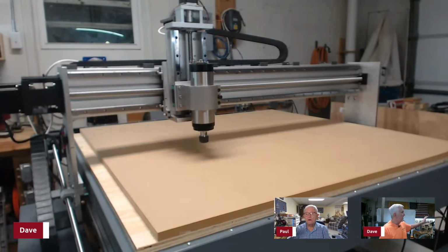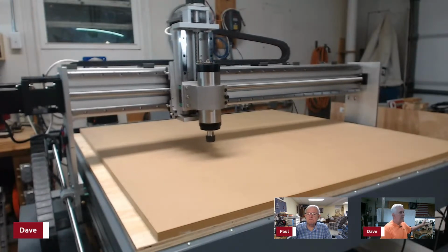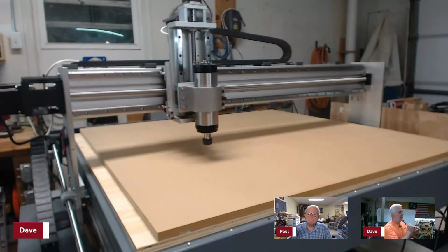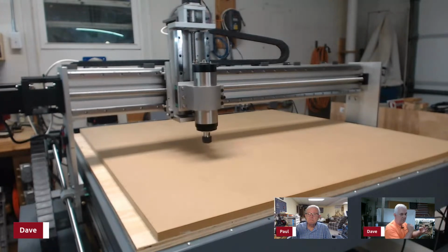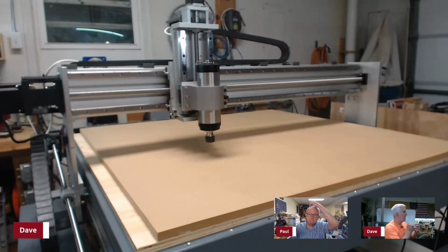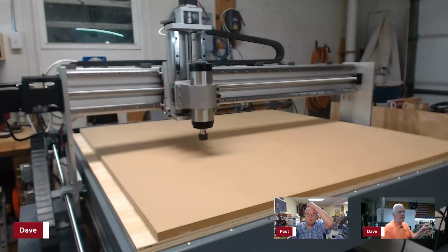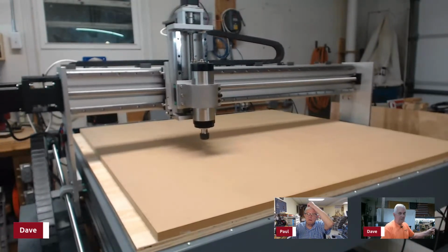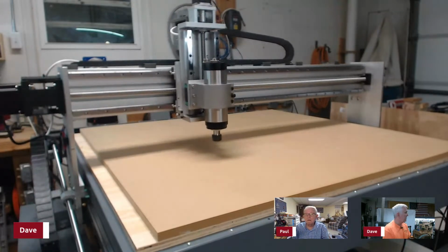And then there's the other block similar to that one, but they call that a BK12. And it's kind of the same thing. It's got a bearing that you slide that into the ball screw through. Then it's got a nut that threads onto it to hold that on there. And then it has, I don't know, probably about an inch or inch and a half of 10 millimeter plain shaft sticking out, and that's what you hook your coupler to.